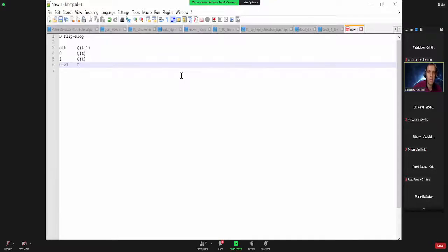So basically, you have the clock edge, okay. And during the clock edge, the output may change its value, because if the previous output was 0 and D is 0, of course it doesn't change its value. But it may load the new value of D, okay, and in this case it's on the positive edge of the clock.